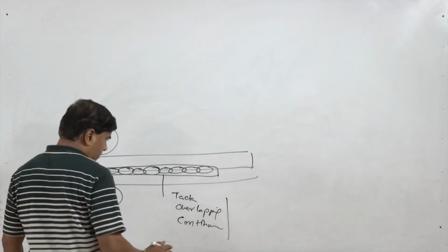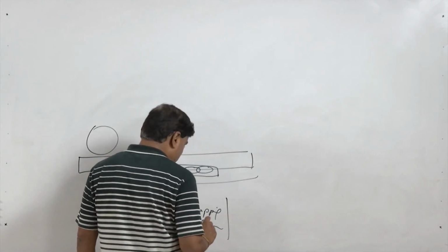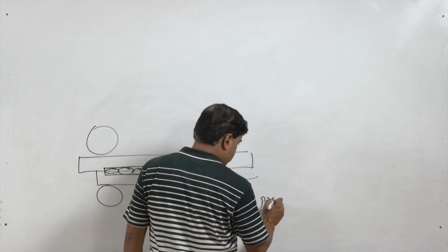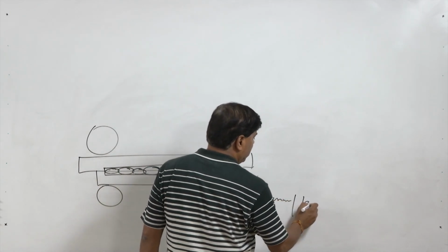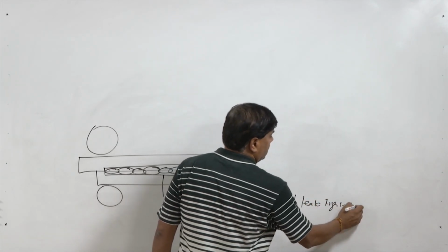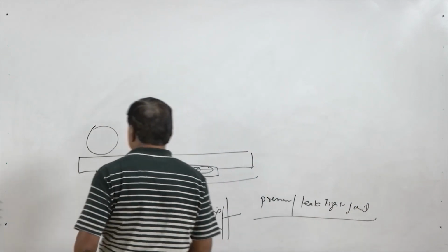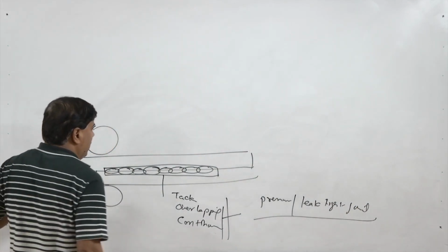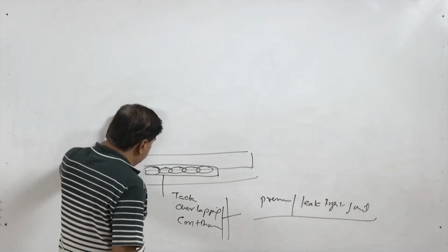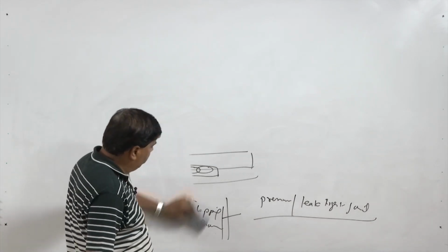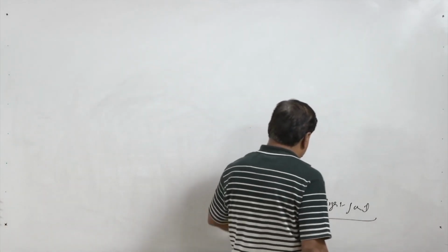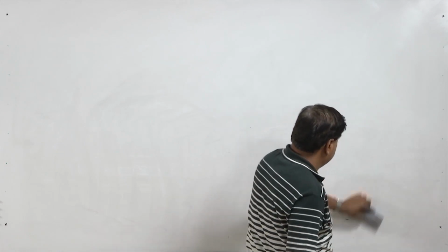Continuous or overlapping types of seam welds are normally used for making pressure-tight or leak-tight joints of sheets, mainly for tanks, and wherever it is required that the joint is leak proof, the seam weld is made. That also works in the same way, on the contact resistance heating principle.